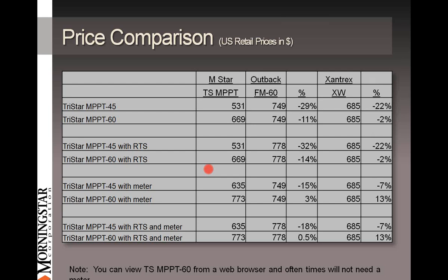Because using our dip switches, you can set up the battery that way. You don't have to use the meter. And in a lot of cases, the dip switches can be far easier to set up the battery too. It doesn't require a lot of setting up and navigating the menu system of some of these controllers at every single site.